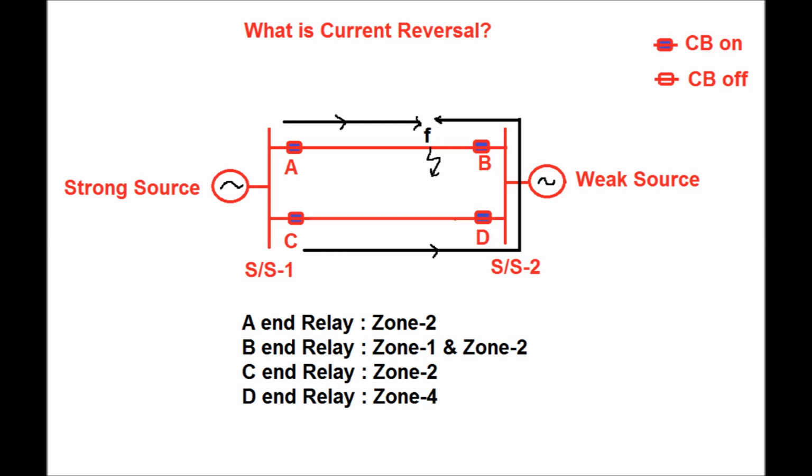A fault occurs at point F, which is very close to point B and far from substation A in the circuit AB. Due to the fault at point F, the relay detection for the different ends of both the circuits is shown in this figure. This fault point will be located from the substation A relay at zone 2.